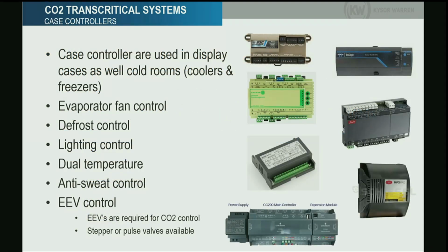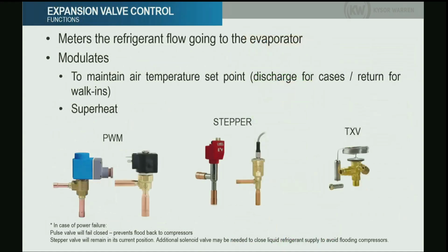Case controllers, there are multiple case controllers from different manufacturers. They basically operate the same. Some of them have different features, but basically they control all of that part of the case: defrost, lights, anti-sweat, temperatures, everything. Expansion valves, electronic for CO2, no question about that.